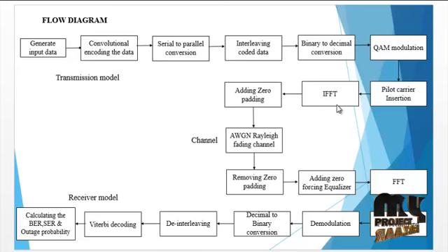Modulation with the IFFT, the inverse Fourier transform function. The modulation of data into a complex waveform occurs at the inverse Fourier transform stage of the transmitter. Here the modulation schemes can be independent of the specific channel being used and can be chosen based on the channel requirement. In fact, it is possible for each individual subcarrier to use a different modulation scheme. The role of the IFFT is to modulate each subchannel on the appropriate carrier. This is the zero padding: it consists of appending zeros to a signal before the transmitter sends it over a channel.